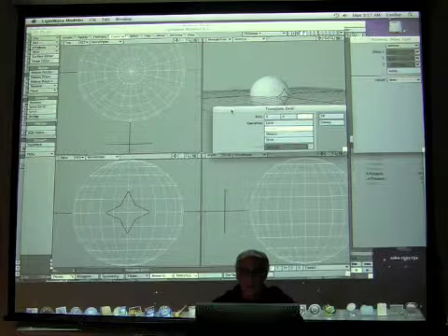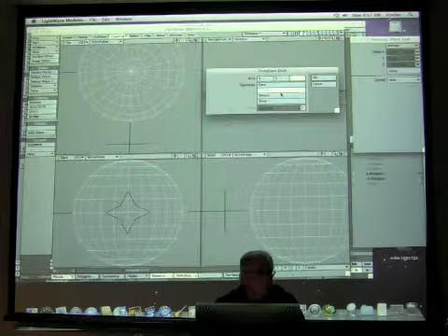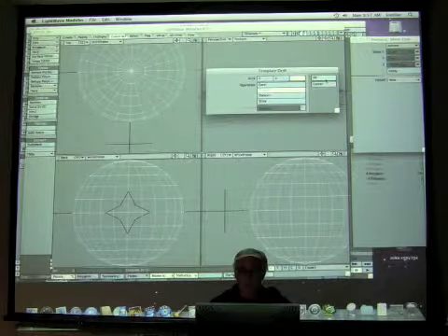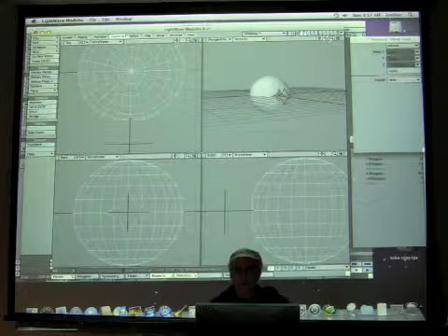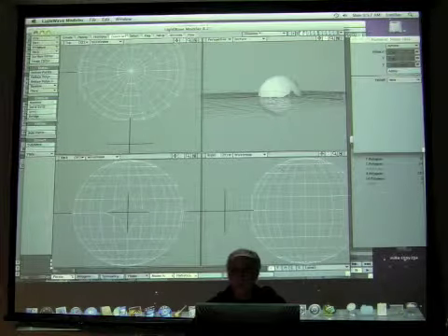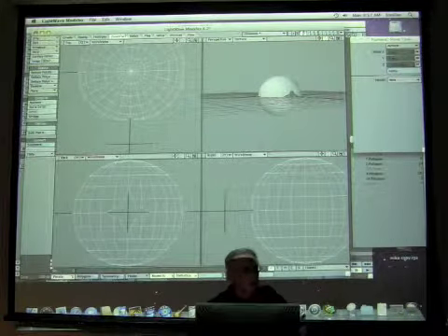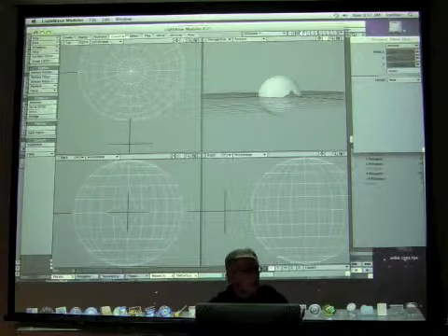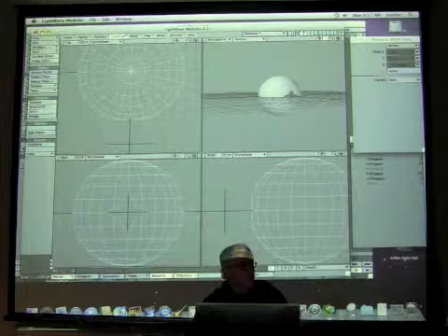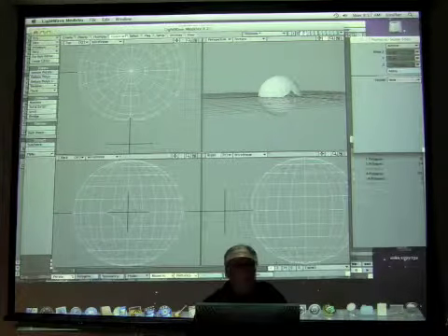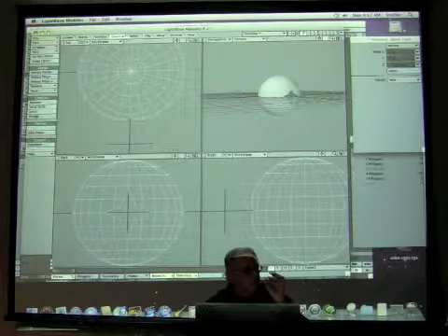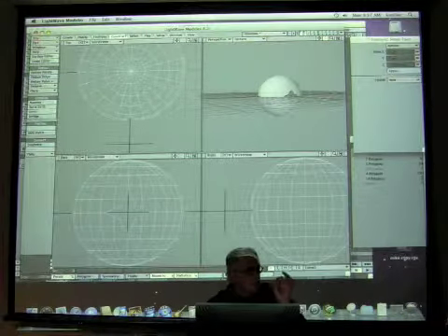Let's select tunnel. What do you think will happen with tunnel? It just pokes a hole. It makes a tunnel all the way through. And you can see you have a tunnel all the way through. Cuts it all the way through. And remember, you don't see inside it because the sphere by default is one-sided. Lightwave assumes you're only going to see the outside of the sphere. So if we were to make it a double-sided sphere, you would see the inside, just like looking inside the shell of an egg, an eggshell.